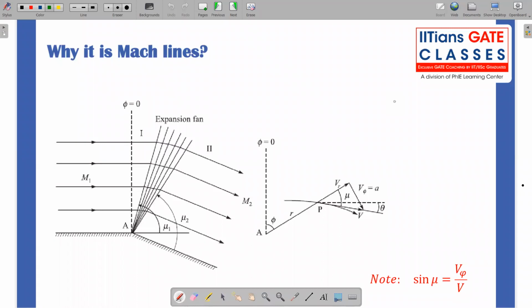Okay, so let us come back to the geometry once again. Here you see I have a supersonic flow with M1 Mach number in the upstream, which is greater than 1, and which is seeing a gradual corner which is deflecting away from the flow direction. In this scenario, one would expect that flow to accelerate. This part we will go into in detail when we talk about intakes or the supersonic nozzle or diffuser design.